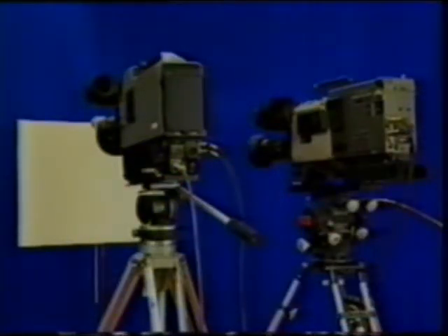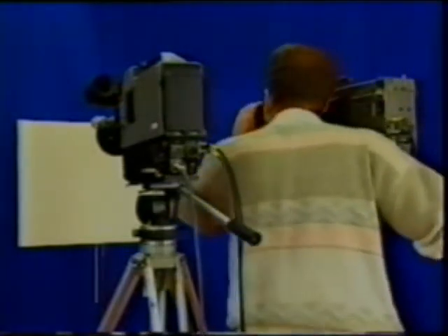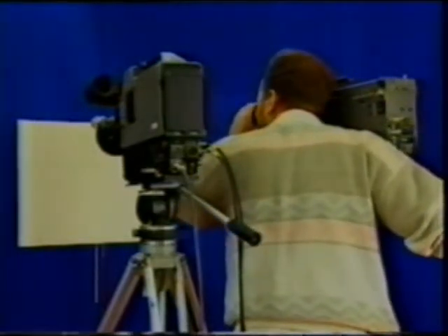Many times in a studio, you'll want to color match two cameras. This is accomplished by performing a manual white balance. Start by pointing two cameras at the same white reference. Adjust the iris on each camera to match luminance levels on the waveform monitor. If a color channel in a camera is out of balance, the fuzzy spot on the Vectorscope will be over toward the corresponding color's graticule box.